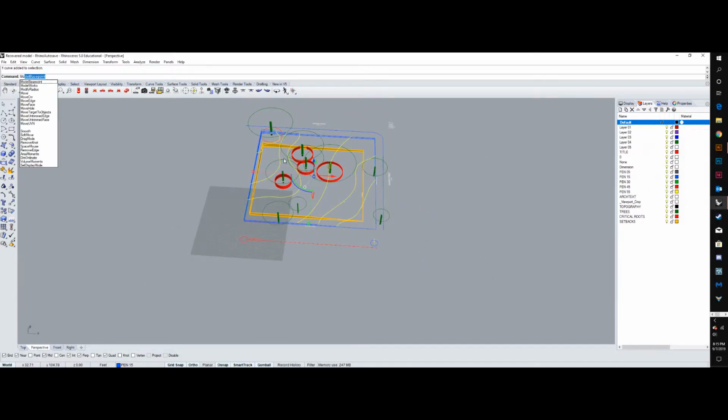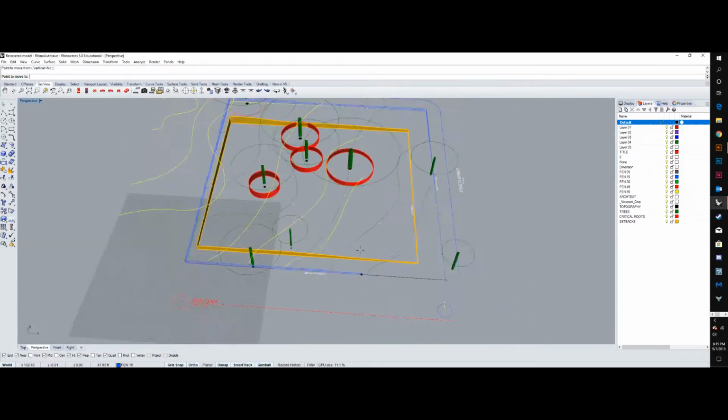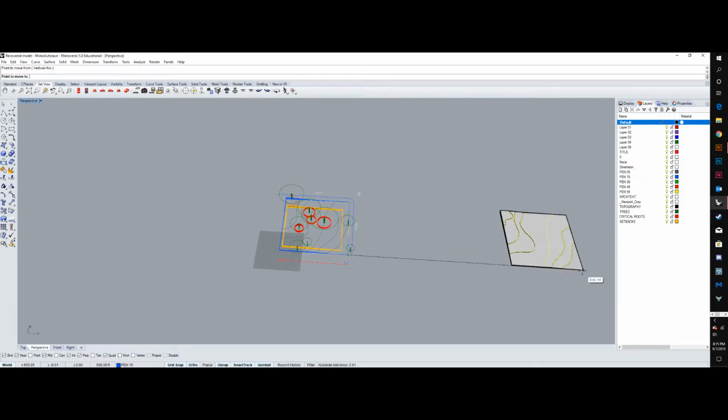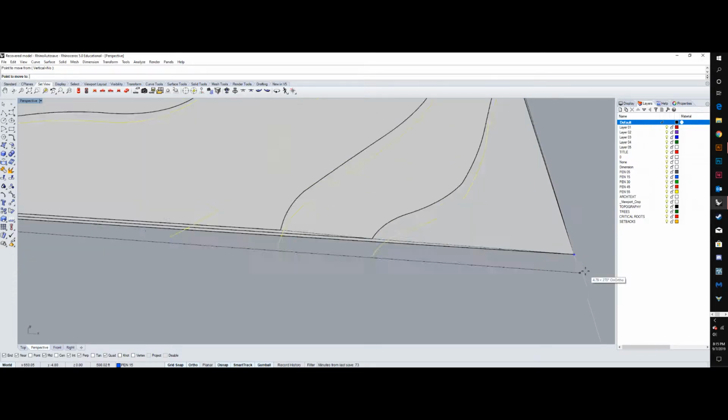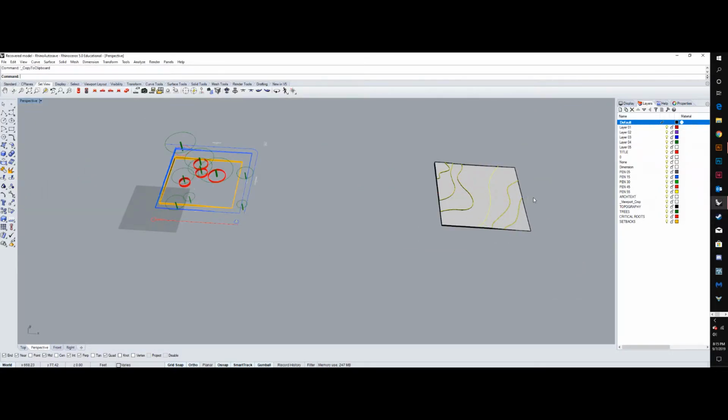Move, or M-O-V, move, okay. I'm going to click a point that I know is going to be the same. And while I have them selected, I'm going to Control C, so copy all of them, and I'm going to undo that because I still need those lines for this drawing over here. So Control C and then Control Z, and then Control V to place them back. So that's a little dance you'll do quite often.